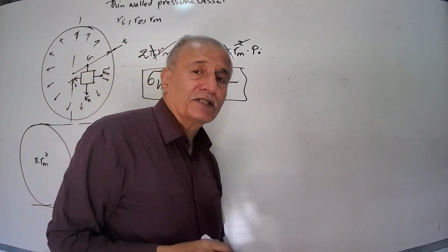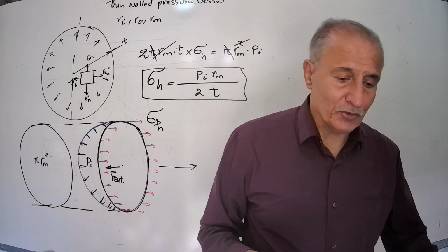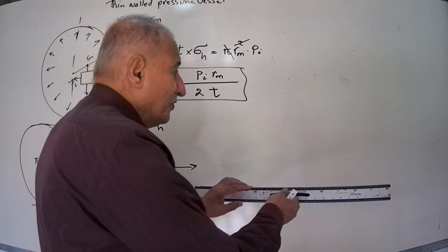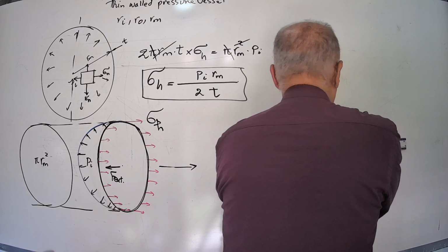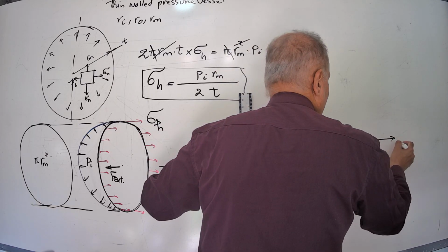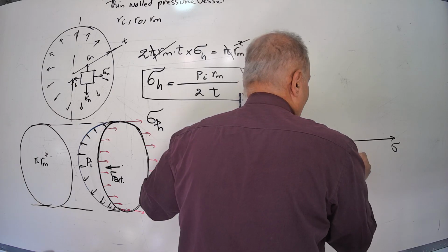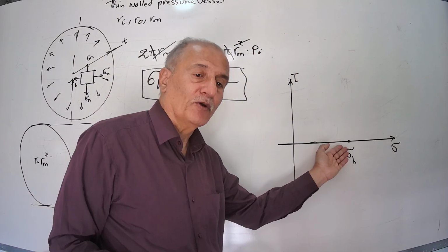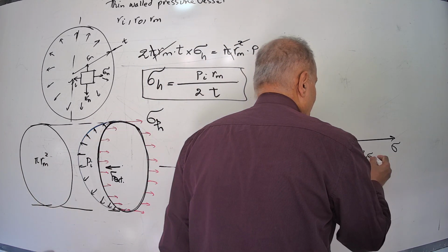And this is the case where the Mohr circle converts to a point. If you draw the Mohr circle for that, sigma 1 and sigma 2, or sigma x and sigma y, have the same value and there is no shear stress. We have only two hoop stresses, sigma x and sigma y, both the same, or you can say sigma 1 and sigma 2, the principal stresses.